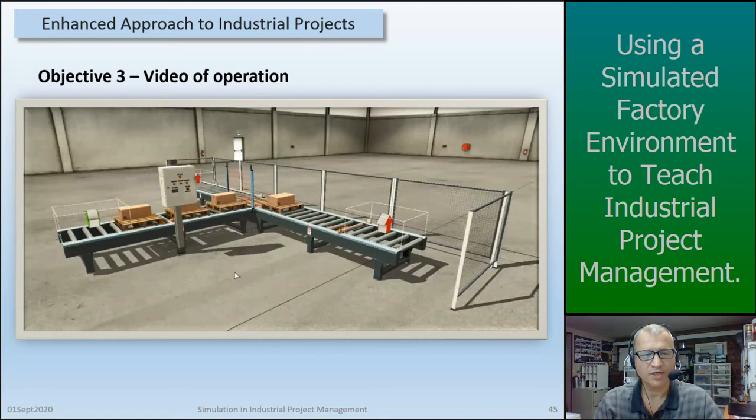Now you'll notice one change in operation. I have to stop the in-feed conveyor. So as soon as the pallet is loaded onto the diverter, the in-feed conveyor has to stop to allow me to divert that box left or right. But as soon as that box and pallet is clear of the diverter, I can shuttle the next one in. Okay, these all seem to be high boxes and they're all diverting to the right.